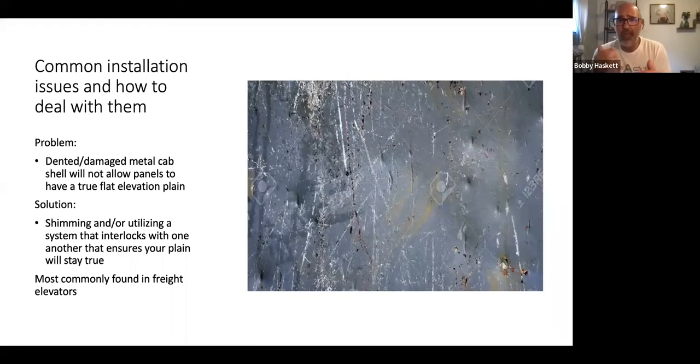In our system, we've seen where you can skip an area up to 2 feet wide that's dented in real bad, because you have like 40 different attachment points along that entire bracket. It can really help you once you tear that down and you see it. I know we send shims with our systems, and I know a lot of other interior companies do as well. Make sure to utilize them when you're doing your installations.